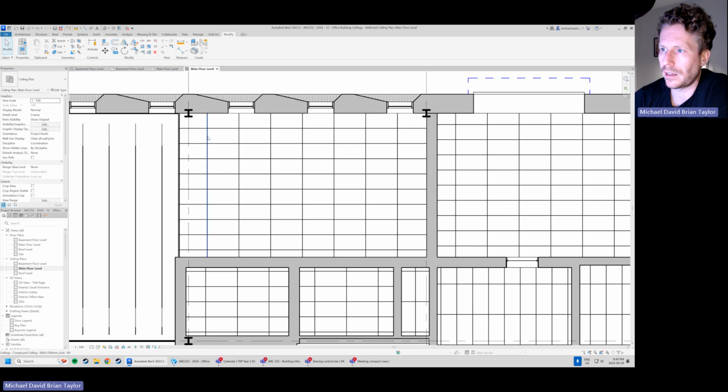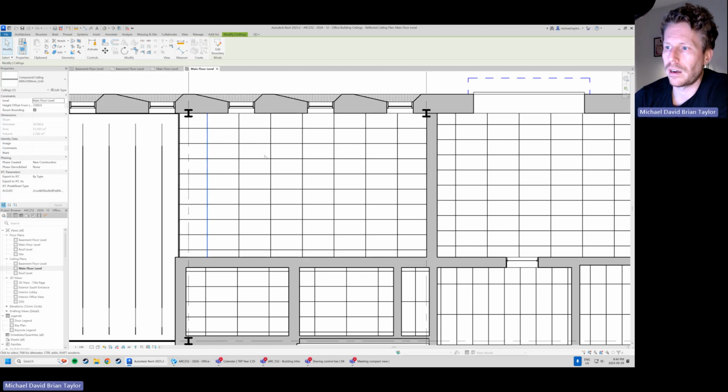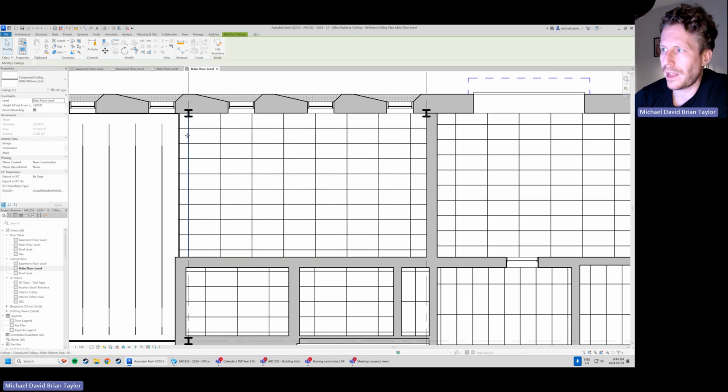So if I just, again, I'm going to click on one of the hatched elements here and click move. Same thing, move it here. Maybe I want to line it up to a grid line. It's going to snap, boom. Pretty clean, lines up with my grid line. Maybe that's cool.